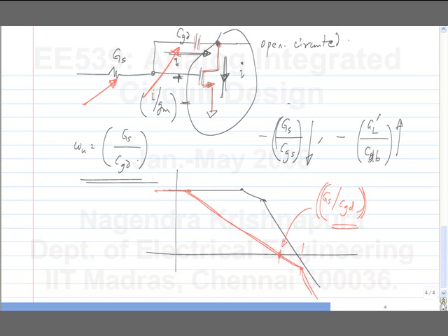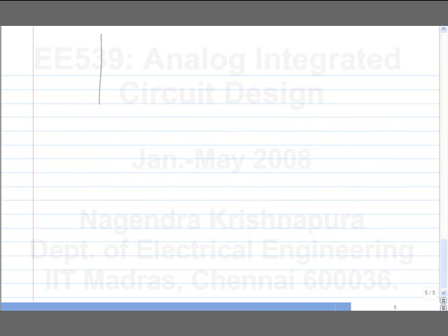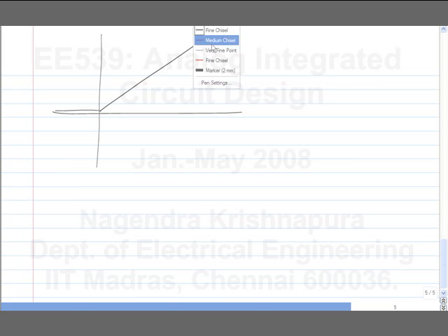Or as we saw earlier in the course, if you have an ideal integrator, the time domain response will be like this. If you have a right half plane zero, what happens? It jumps down and goes back like this, right? So essentially, if this was the element that was giving you feedback, effectively the feedback is delayed. In fact, initially the feedback is in the opposite direction to what you want, and it goes back. So effectively, you can think of it as either delayed or being in the opposite direction. So it can trend to instability.